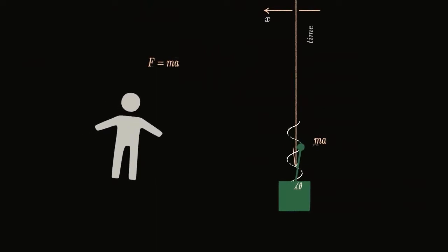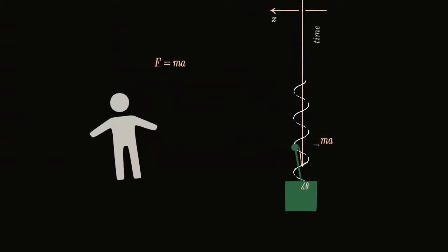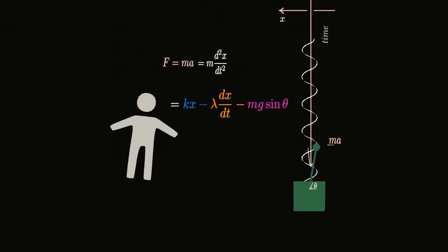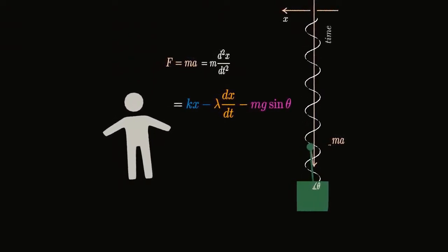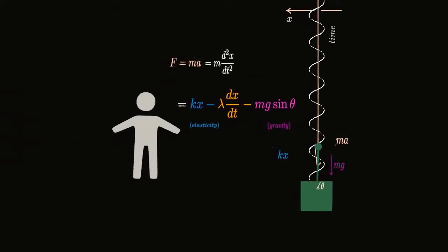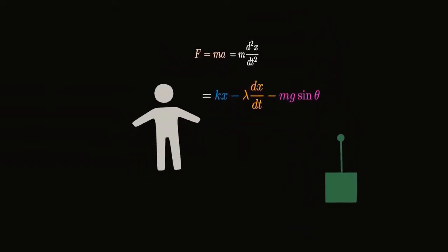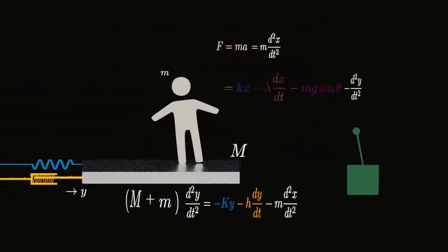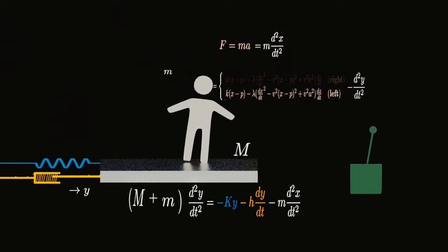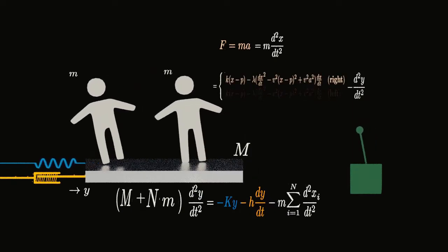We model the motion of a pedestrian's center of mass on the supporting leg falling sideways as a rigid upside-down pendulum. Newton's second law yields an equation for the acceleration side to side. When a pendulum swings, it's subject to gravity, elasticity, which controls the frequency of the oscillation, and damping, which reduces the amplitude. We extend this model to interaction with a vibrating platform, add various complexity to make the model more real and self-driven, and sum over the force of pedestrians to add the crowd.